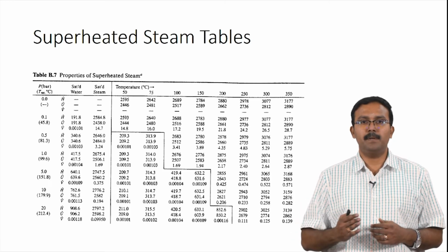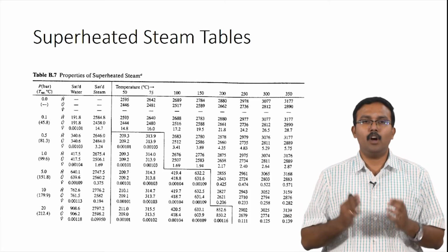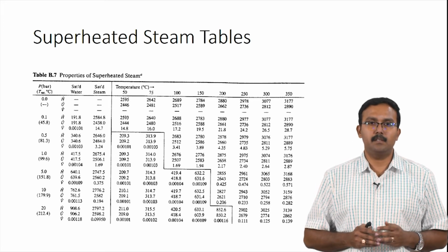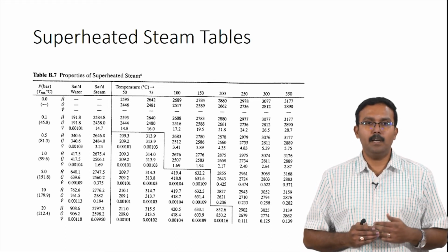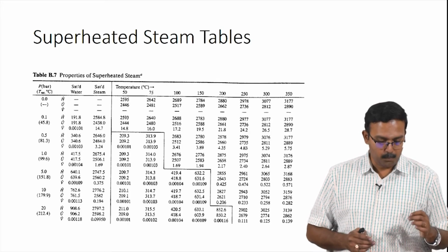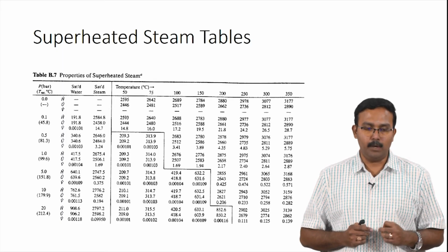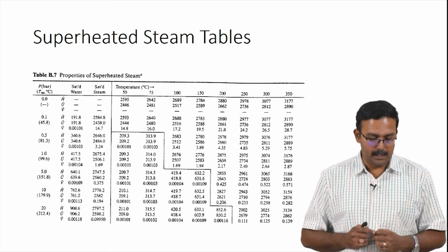After that, the temperatures which are given are all different temperatures, not corresponding to the saturation temperature. So, for example, if you were to take the third data point for pressure, which is 0.5 bar, you have a saturation temperature or boiling point given as 81.3 degrees Celsius.